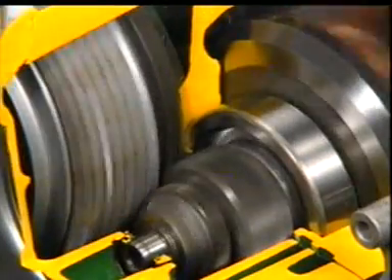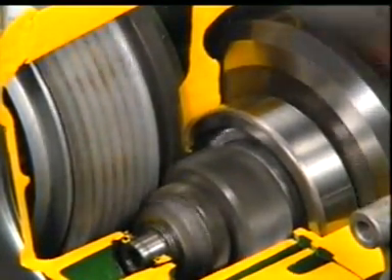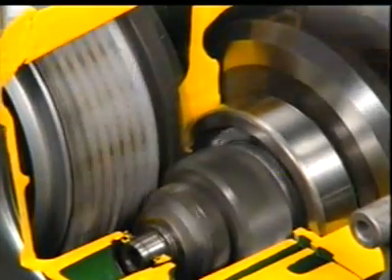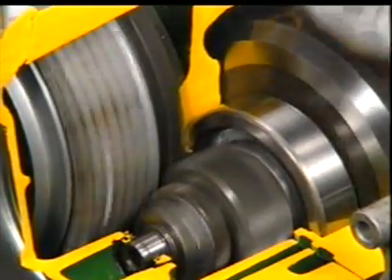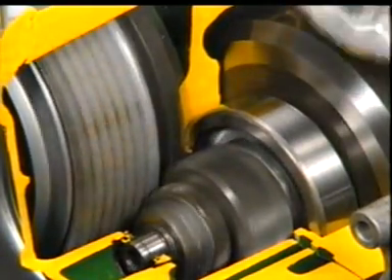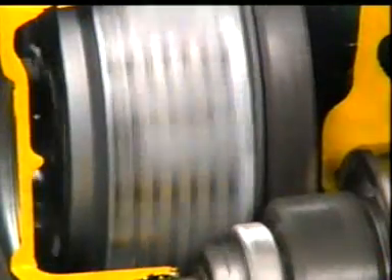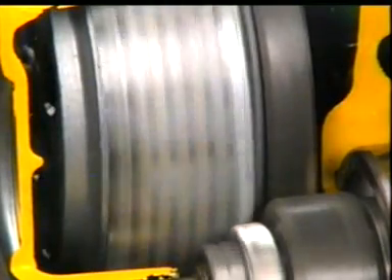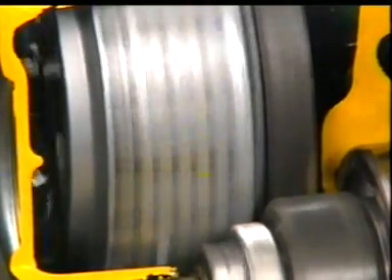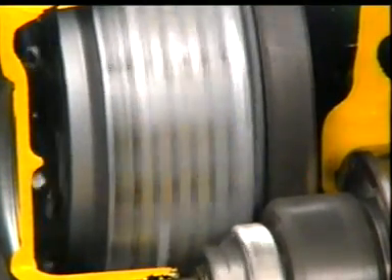The crankshaft speed can reach as high as 10,000 revolutions per minute. By providing this primary reduction system, however, the speed at which the countershaft rotates can be suppressed even when the engine is running at high speed. And this keeps the inertial force on the gear itself low. When the clutch is disengaged, the gear rotation slows promptly, so that gears are changed smoothly.